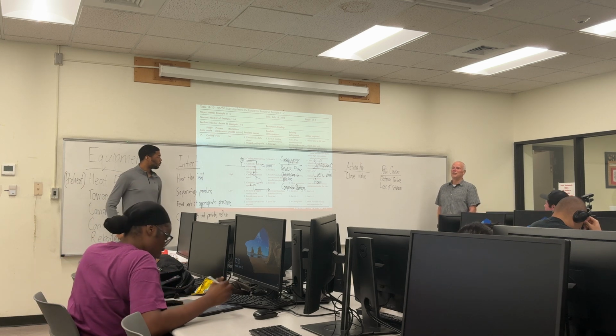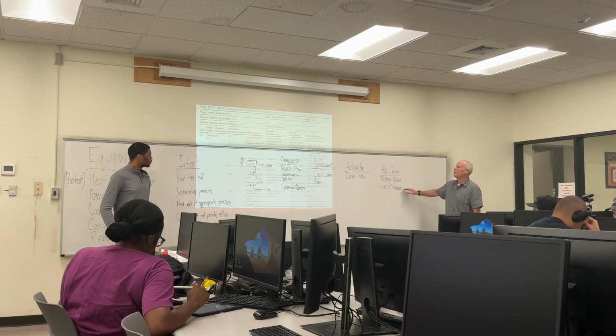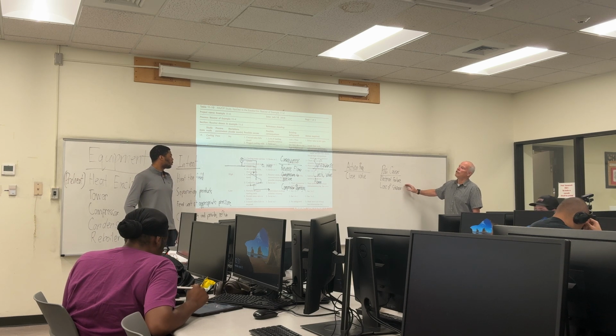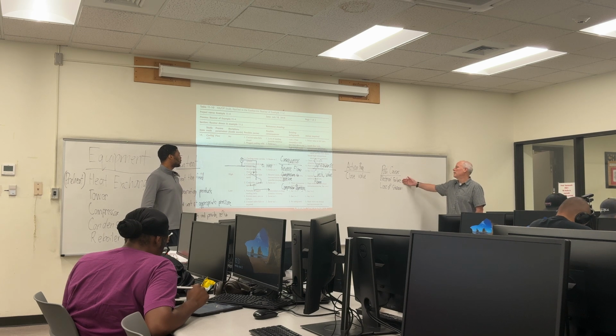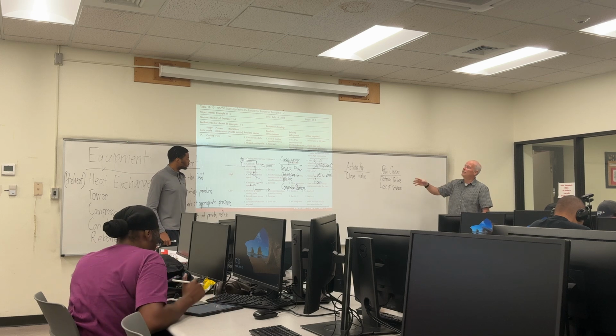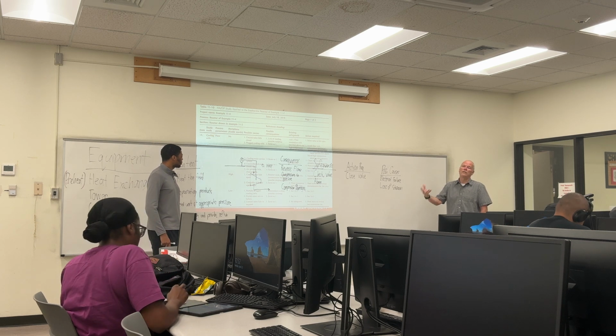Control, and you lost control, it's going to fail. So we've got loss of steam, but it's not as simple as loss of steam. You almost have to figure out what scenario caused you to lose the steam. To be a scenario, it needs to say what caused it. Electrical, that's enough, but then you have to say, well, what did that cause? So you got electrical, and that caused the PLC to fail, and then all the control valves shut, all our steam control valves on those turbines closed.